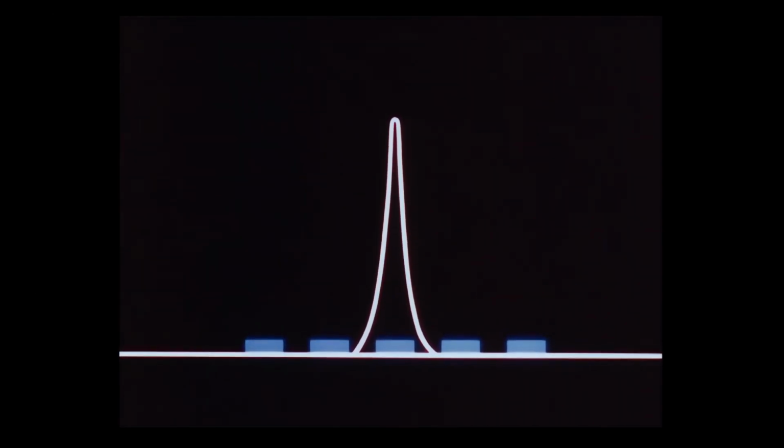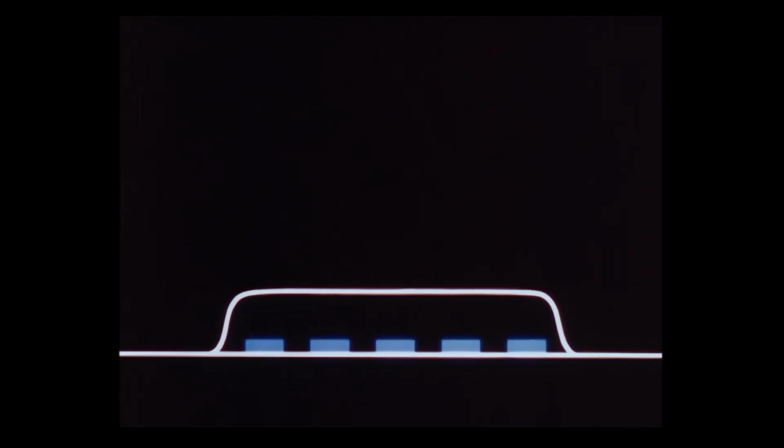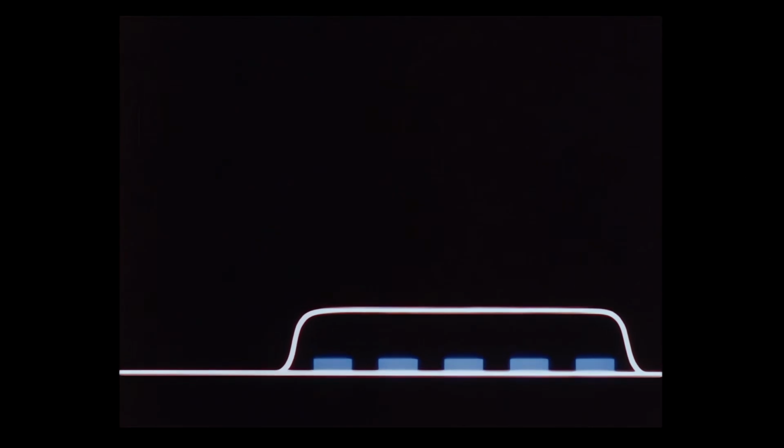This requirement is not achieved with the simple dipole. This antenna has a high efficiency at a spot frequency. That is to say, a high Q. To increase its bandwidth, we must lower its Q. This process is known as broadbanding. Let us see how it is achieved.